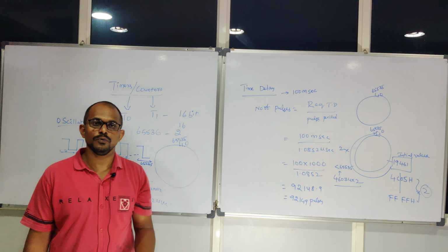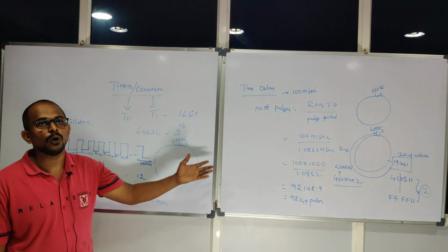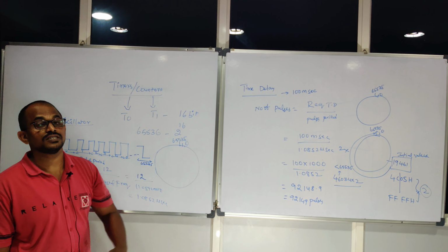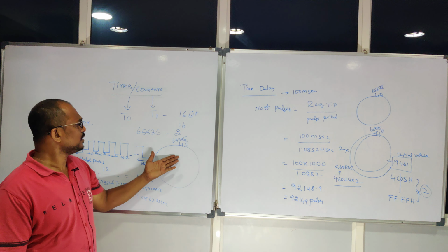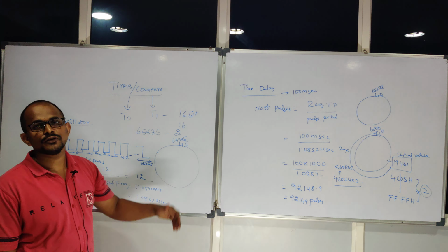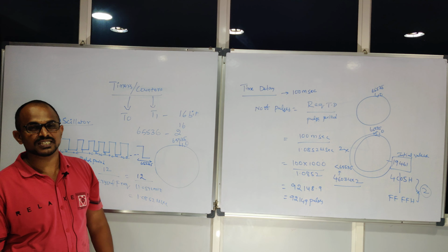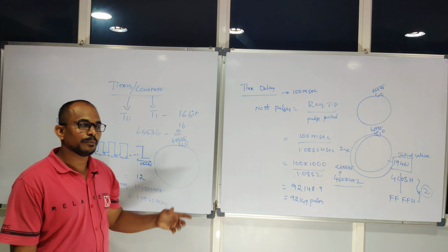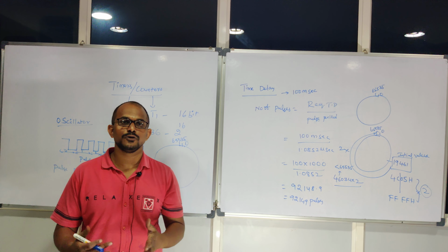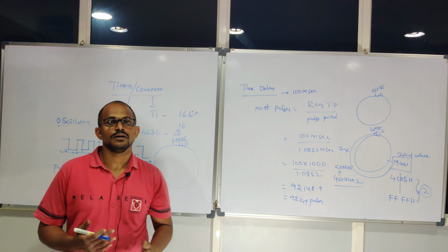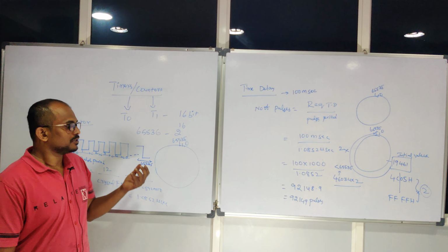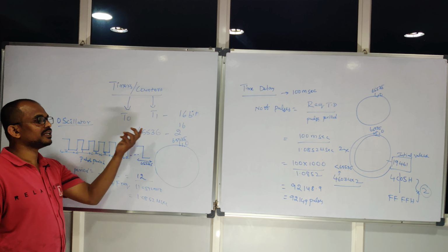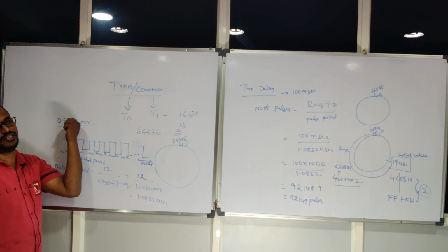But if you want to go with this, you need to know how timers work and what maximum count they are going to count. As per capacity, you need to decide that maximum capacity or maximum count. Timers are also doing the same procedure to give time for us, just by doing a counting process. So what are they counting internally? Timers are counting internally the pulses generated from the oscillator.